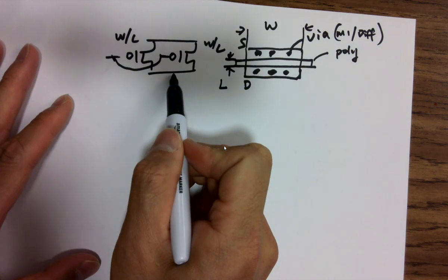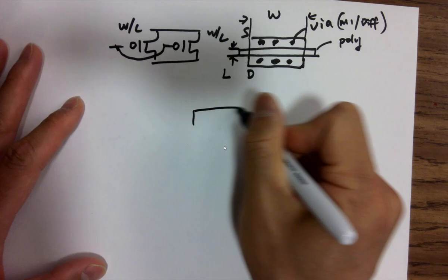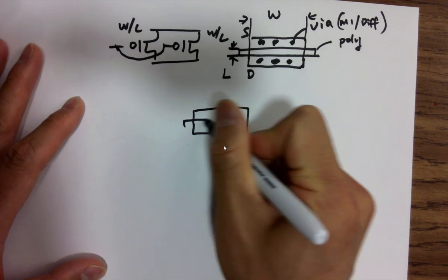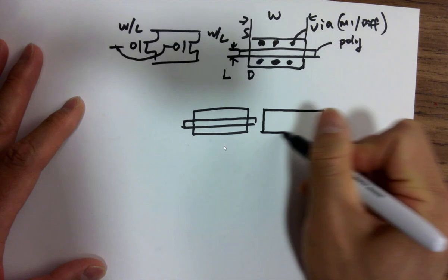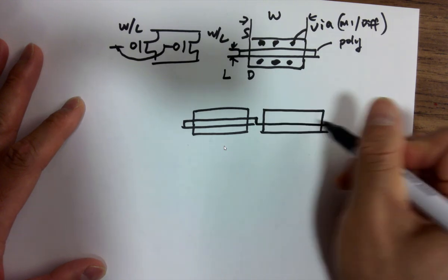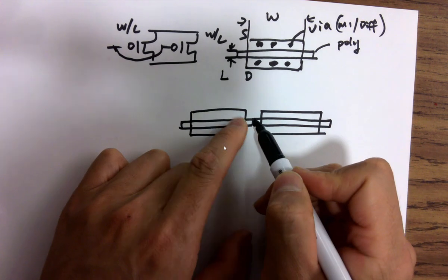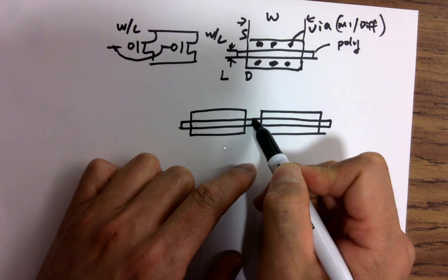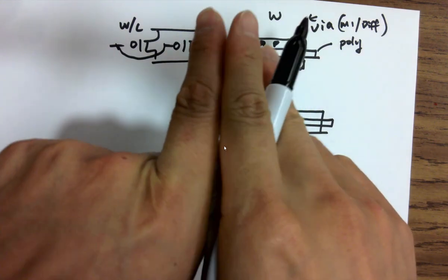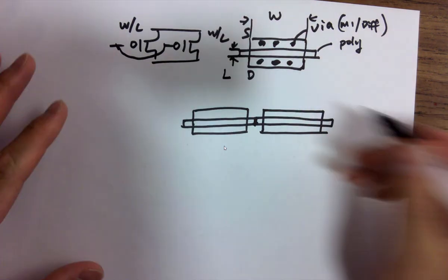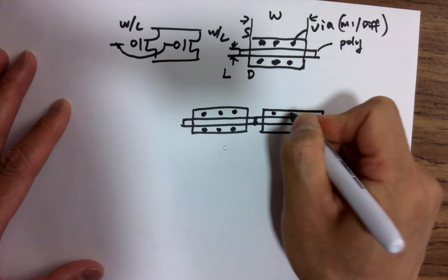So for this type of circuit, it's equivalent to this. And in Cadence, you just directly place them next to each other, and you don't have to let them overlap, but just put this boundary on top of this boundary, so they are exactly matching. It's exactly next to each other.